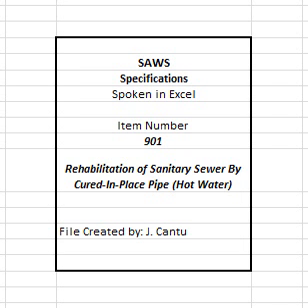B. The impregnated tube shall have a uniform and homogeneous thickness that when compressed at installation pressures will meet or exceed the design thickness. C. The tube shall be sized so that when installed it will tightly fit the internal circumference and length of the original pipe. Allowance should be made for circumferential stretching during inversion.